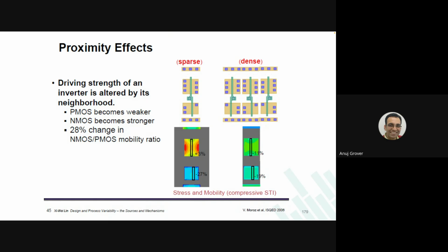Similarly, about the write driver, we looked at the constant negative voltage write driver paper that day. Now, that was just the schematic that they showed you. But when you make the layout, on the replica side, the replica write driver has to have similar proximity effects, similar structural variations as the actual write driver.